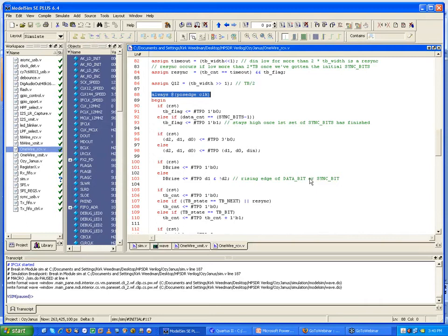Well, in our last lecture, well, pre-lecture I guess it was, we talked about how I create a 1 clock wide pulse based on the rising edge of a signal. And should I go through that again or not? That's what these flip-flops here are. They create the signal called dB rise. Should I run through that or just continue on?